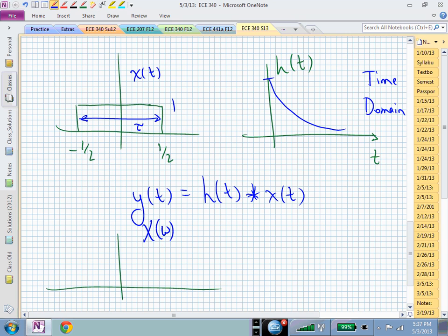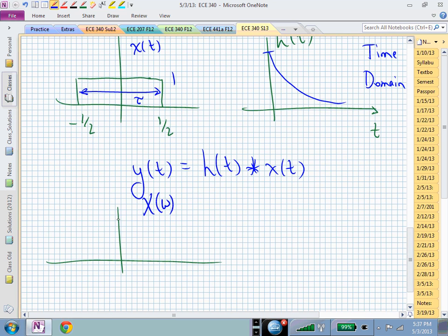What's a pulse give you? That's now this sinc waveform, and that now is, let's say, as a function of omega. With this particular point, the first crossover is 2 pi over tau. And this one is then minus 2 pi over tau.